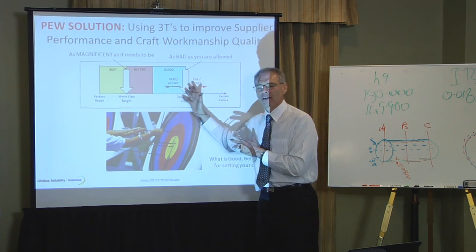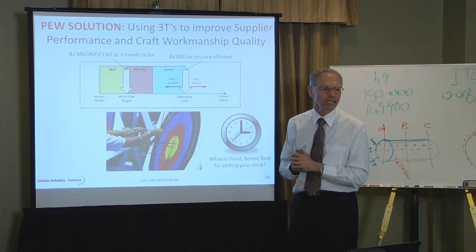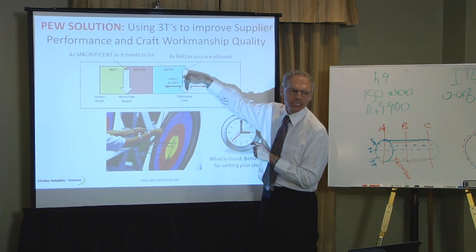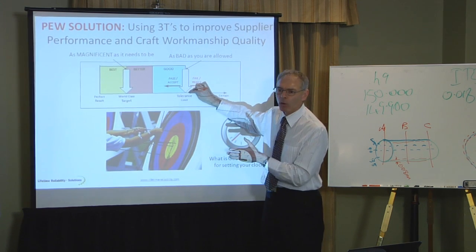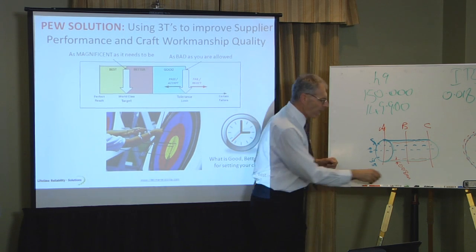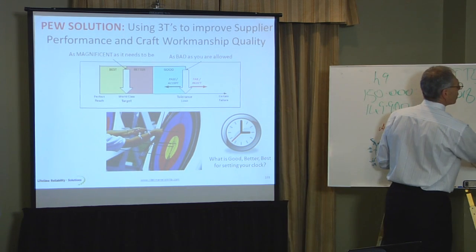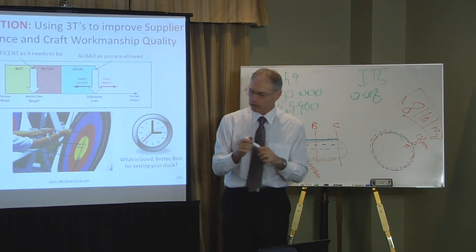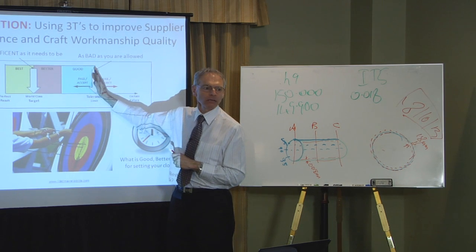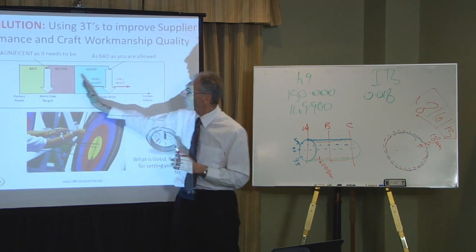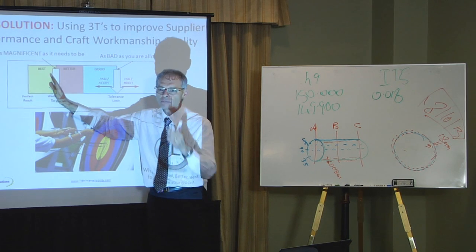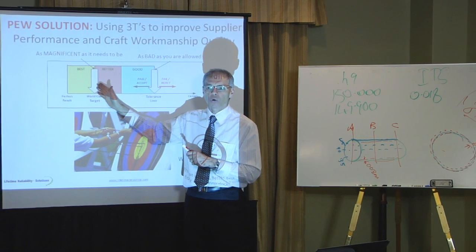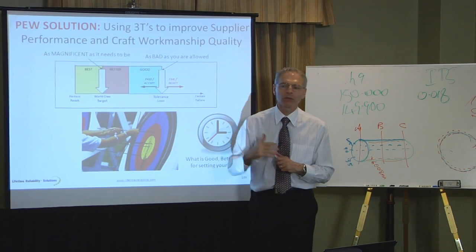Good enough isn't, we know that, it isn't good enough, but it's what we are today. And typically what I say to companies, set this value here as what the OEM sets. Whatever the OEM says is acceptable, do it. So if the OEM says that 18, 16, 13 ISO count is acceptable, do that. So this figure here is 18, 16, 13. We know it's not good enough. We want to be here, 14, 12, 10, whatever the case is. So I'm going to have 14, 12, 10, maybe even 12, 12, 10, 9, depending what I want to do in terms of pushing the limits.